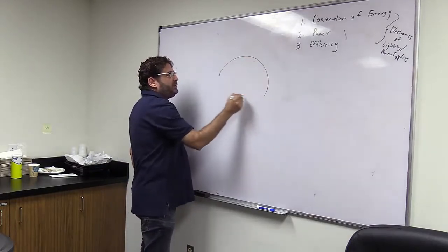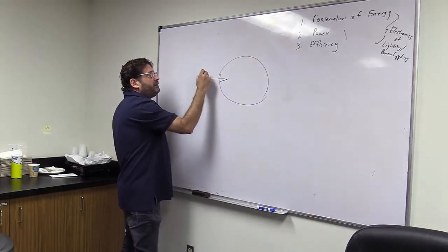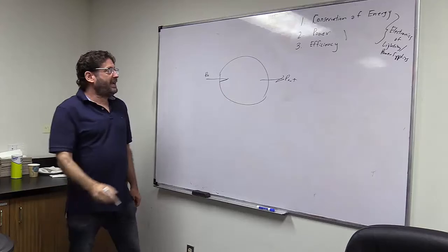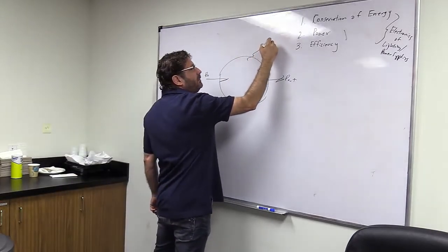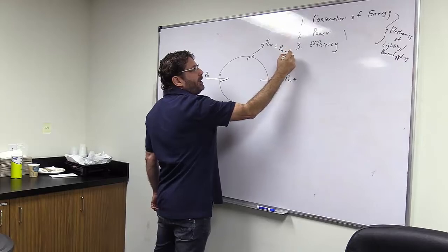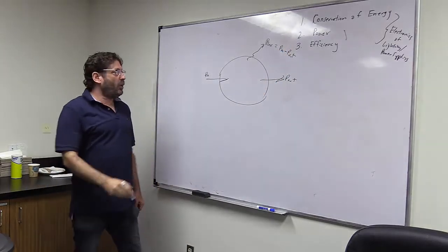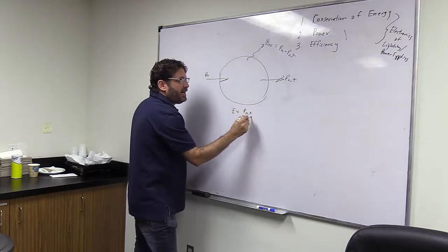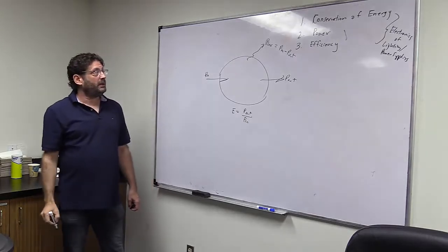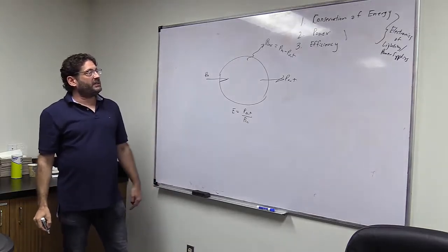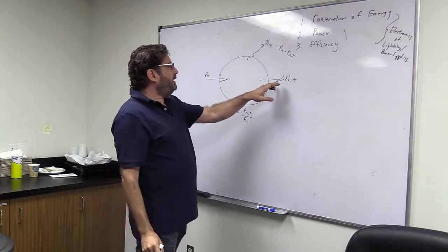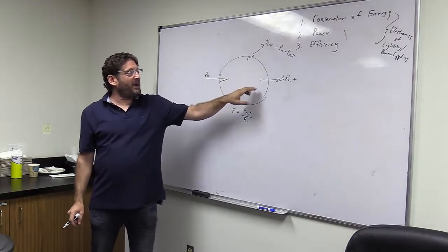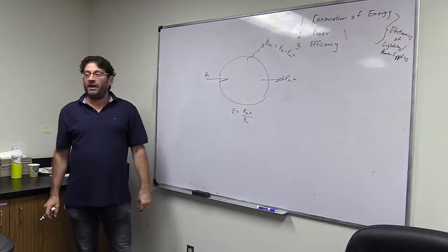So we talked about this, which was if I know my power going in and I know my power going out, I can tell you what my losses are, because this equals power in minus power out due to conservation of energy. And I know what my efficiency is, because I can say it's my power out divided by my power in, right? What's kind of interesting about this is that if I don't even know how much my power in is, but I do know my power loss and my power out, I can also derive this, right?